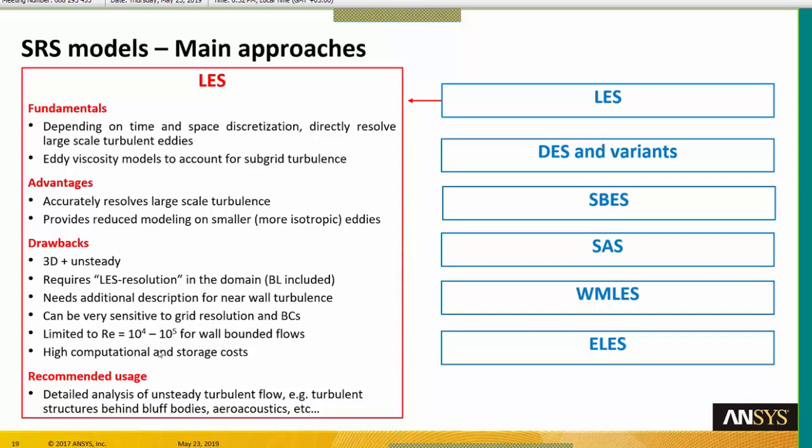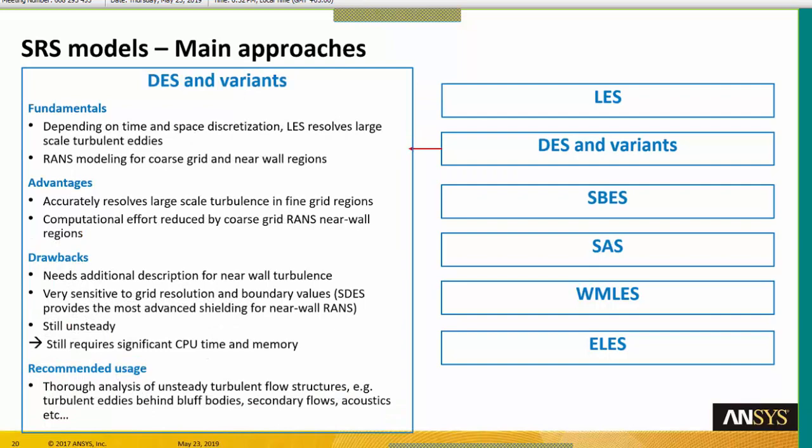So the typical scenario of usage for LES is when you want to study highly unsteady turbulent flow characteristics, for example, turbulent wake flow, aeroacoustics, of course. Many situations where a large amount of eddies are created. In fact, many industrial situations can benefit if you want the details of these transient phenomena. But usually it's very expensive to do LES, and so we revert to DES, and you have some variants for DES as well.